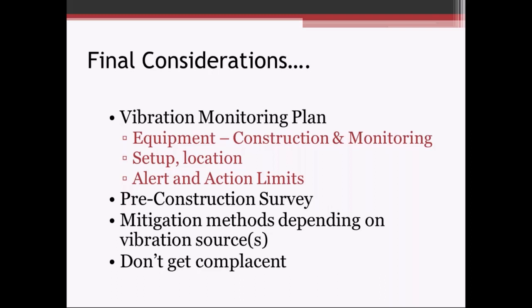If you don't, that one event that you don't take a look at, that you don't analyze, that property owner is going to say, oh, you didn't address this one, or nobody took a look at this one. That's the one that may have caused some issues. So just don't get complacent. Make sure that the vibration monitoring plan is all part of a risk management program. So make sure that it's not just a 3-ring binder that's taking up space on the corner of a desk.